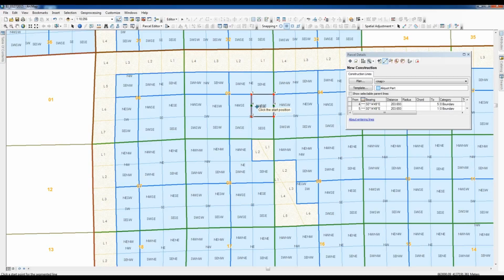Now we have 2 points where we can utilize this same tool to create the dividing line. In the window over here, you can see that those lines were equally divided. So that it's 2 midpoints, a midpoint on the east line, midpoint on the west line, which should be the proper aliquot division of this polygon.